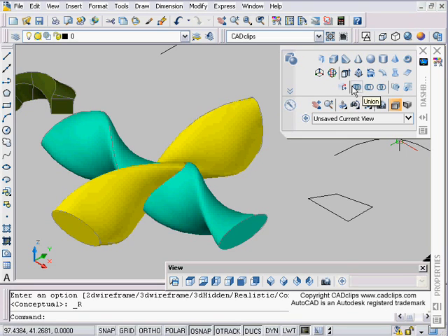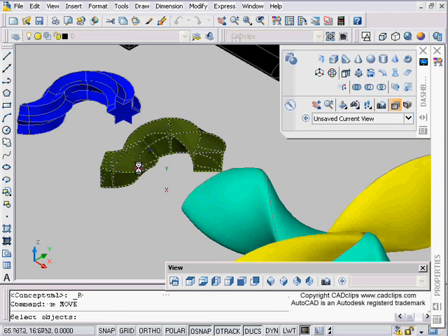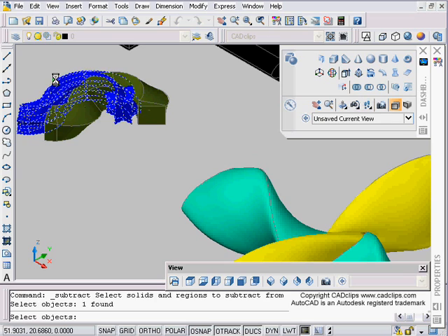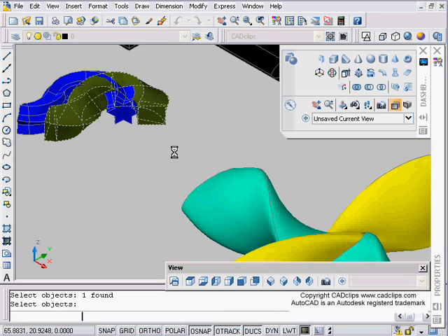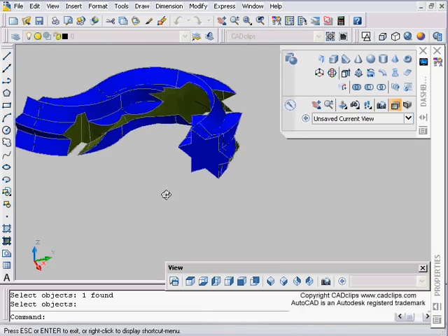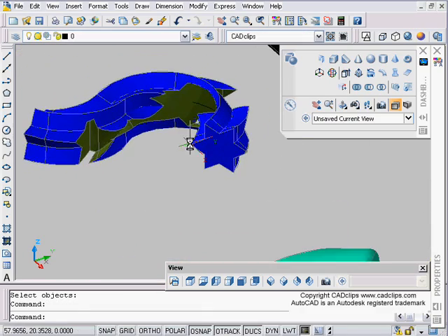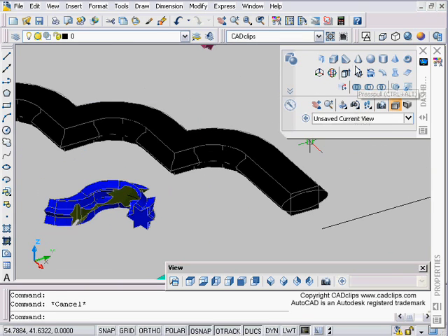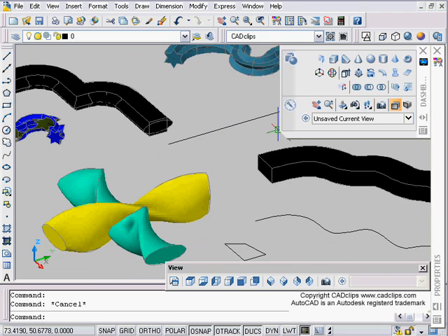Don't forget about our Boolean operations of intersect and subtract and union, which is where we can take these objects and start to blend them in with each other, and then maybe do a subtract from this, enter, this, and then it'll actually remove from that. And of course, the more complicated the shape you have, the more difficult it's going to be. But as you can clearly see, it does the Boolean operation there for you. So take these tools that we're using here, loft and sweep and all these tools, and combine them together to build your models.